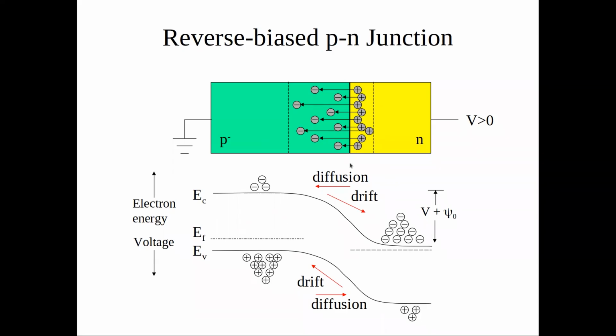So everything, of course, in this PN material is static, is at equilibrium. And this can be done only when the diffusion current balances out the drift current. So at equilibrium, you have these two forces canceling each other out, and everything is then steady.